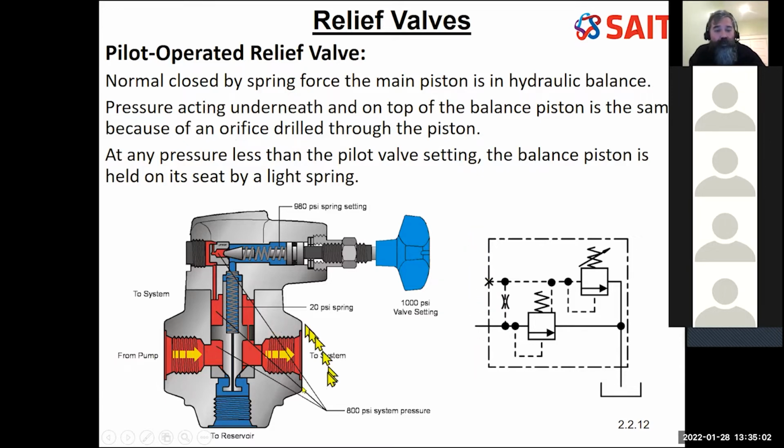Now, a valve without this right-hand opening would be this symbol on the right. I've got fluid coming in, okay, so fluid coming into the valve. I'm going to bleed off a little bit of that fluid through a very narrow orifice. That's the symbol here, okay? Now on a needle valve, we indicate an adjustment, that we can adjust that needle valve. But here I've just got an orifice, it's not adjustable. That's what this is through here.